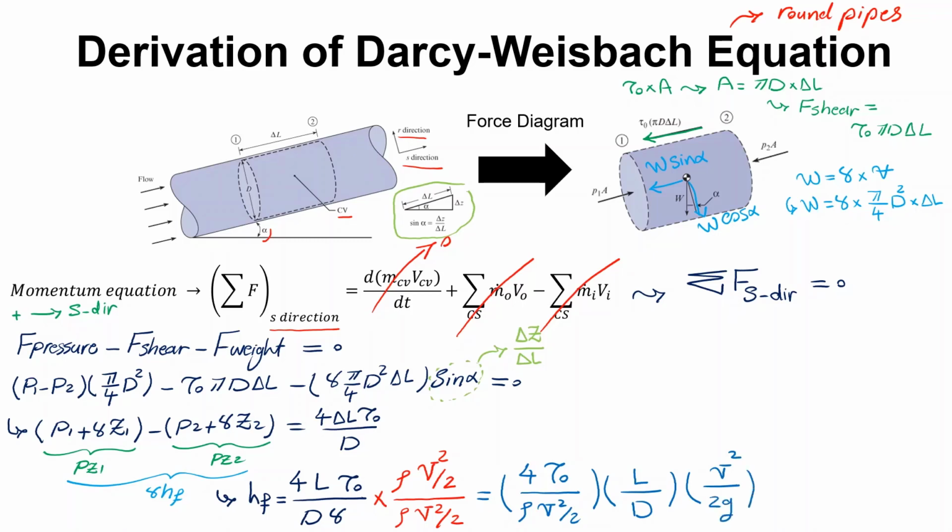All right, so they decided to call this term over here F, or friction factor. This term, friction factor, will take different values for laminar flow and for turbulent flow. But everything else, like length, like diameter, like velocity, you can easily calculate, right? So the only thing that you need to figure out when you are calculating head loss, or HF, pipe head loss, is friction factor.